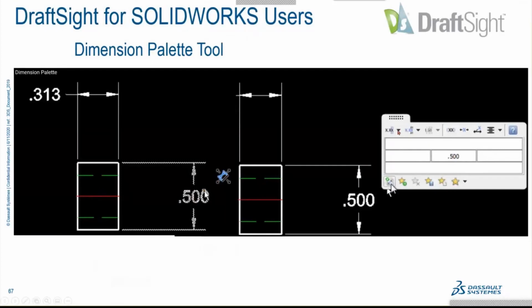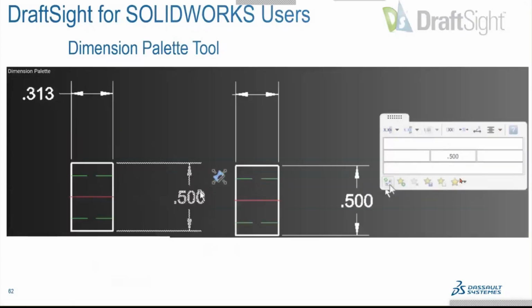I can change my tolerance on this. I can also center something. I can put brackets around it. This centers my dimension in between my endpoints or my arrows. Okay, this either centers it or left justified. I go to help right here. I also can create favorites like I can inside drawings inside SolidWorks as well. So I can create favorites as well.